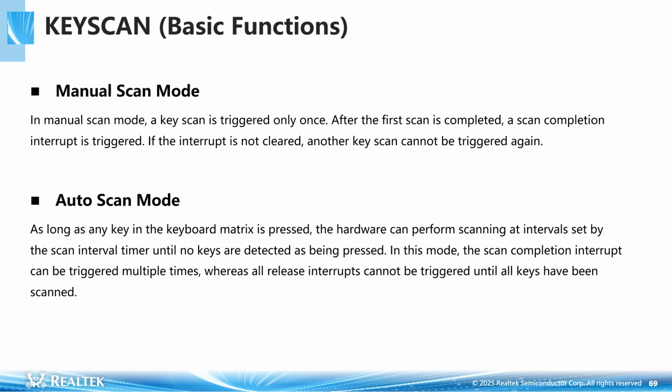In manual scanning mode, key scanning is triggered only once. After the first scan is completed, a scan completion interrupt is triggered. If the interrupt is not cleared, the next key scan cannot be triggered.